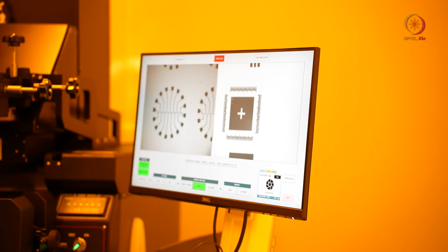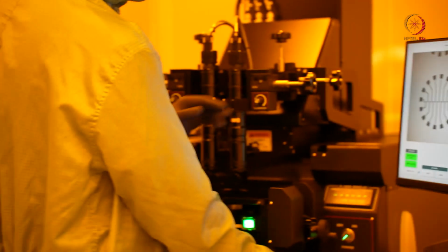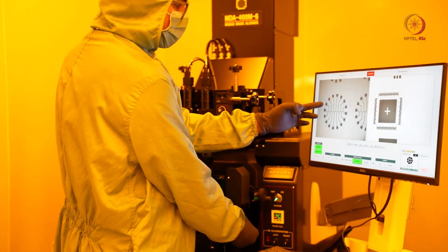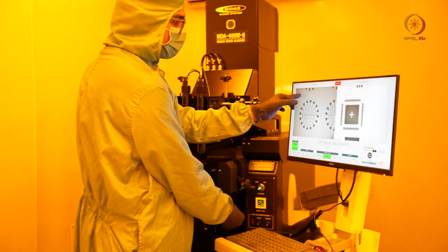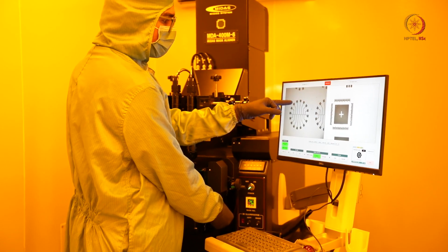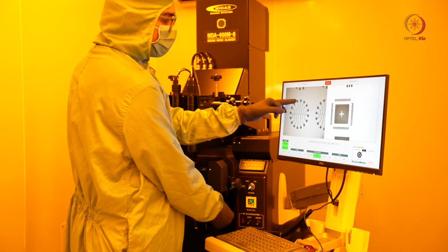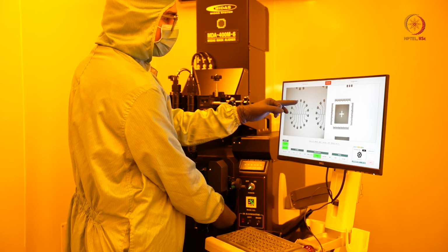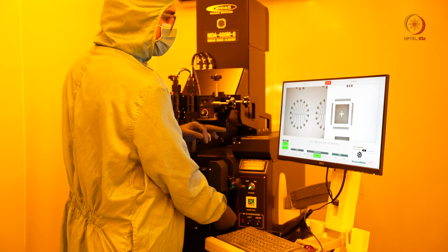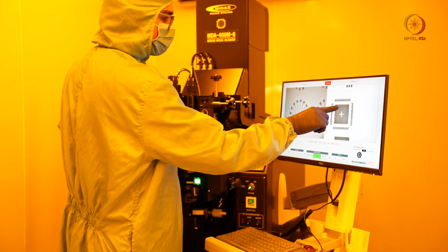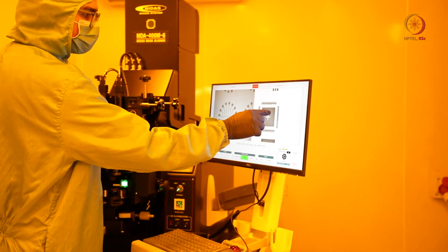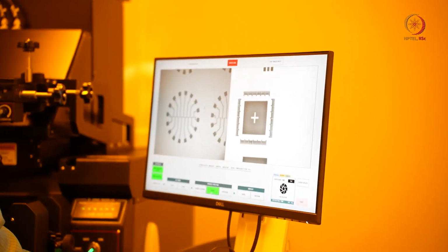Now that we have the samples here, what we can do is the wedge error compensation, which includes lifting up the wafer to a stage where it touches the mask. So you can actually see in the display here. Since this is a dark field mask, the white region that you see is the opaque region, and what you see through the gray color slot is the transparent region, and you can see the wafer there. Now if we zoom in, this was the transparent area, and this is the opaque region. Now this is blurry here.